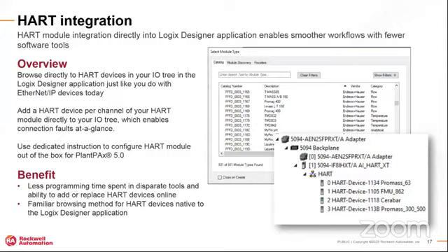So jumping right in, want to start by looking at highly integrated HART or HART integration. With version 33, when looking at Flex 5000 and HART IO on Studio 5000, you can now see this IO from the IO tree itself. In comparison to previous versions, you would have to go in through the add-on profile, and then it would be hidden in the channel. So now having that direct access to see it right then and there is something that is premiered to version 33 of the platform.